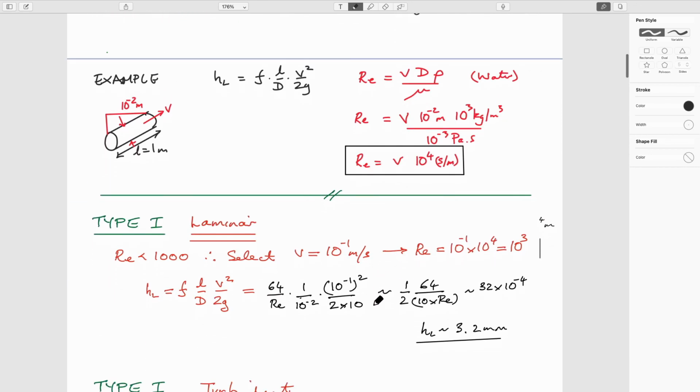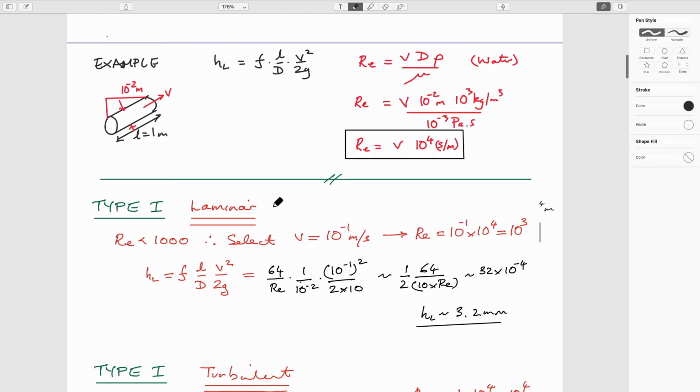And we said that we could do it for some assumed geometry: a pipe that's 1 centimeter in diameter, 1 meter long, has some roughness, and has a head drop between upstream and downstream that we don't know. Then we can try to calculate this head loss term, which would be just the height of the fluid between upstream and downstream, just as we saw, delta Z. And we could do it for both laminar and turbulent behavior.